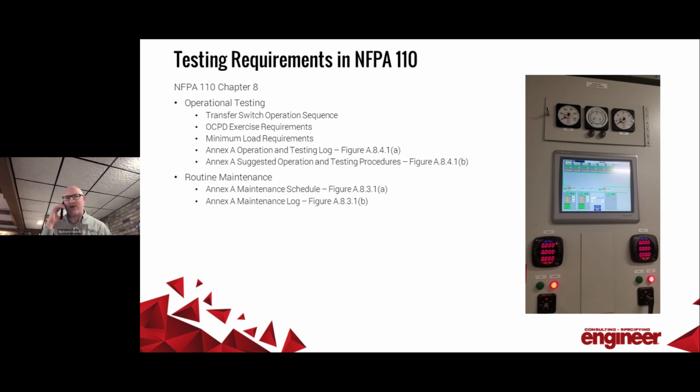We had requests about testing requirements in NFPA 110, and honestly, that could be a full hour in itself. So we're going to save a little bit of time there and remind you that Chapter 8 tells you everything you need to know about the testing and operational requirements. Additionally, the annex has logs, matrices, spreadsheets, and schedules that you're going to need for operational testing, compliance testing, and maintenance. The strongest recommendation is to start with those, refer to those, and then you can, of course, tweak and add as necessary.